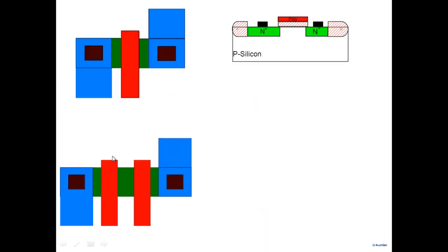Let's look at that. So this is one transistor. I've just drawn an NMOS. Just compare the top structure here, NMOS here. This is my poly here. This is where the channel is. This is one contact. Let's say the drain contact here. And this is the source contact here. Please note that this shows clearly that this N plus region extends all the way here. Wherever you are making a contact between N plus and metal, the N plus has to be there underneath it. The metal is on top of it, and the contact is which makes a contact. Right? So both of them are here.